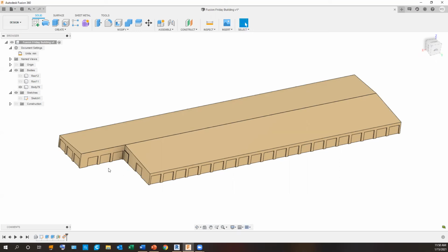But we've actually done it all of the 3 ways, and the way we prefer is to either print it solid like this with infill on a single volume, one print, or split it up into separate bodies and print them all separately. Because when you're working with the thin walls and shelling out the models, we found that there's a lot of processing time that happens after you print it. There's a lot of assembly time. It's pretty difficult to put together. Sometimes you can get some warped walls that you either have to reprint or you have to figure out how to fix after it's printed.